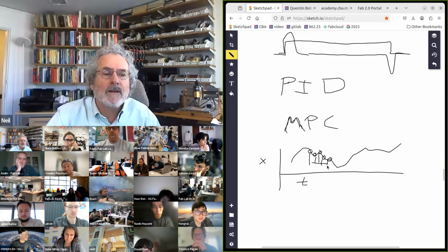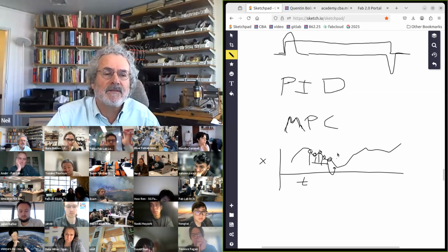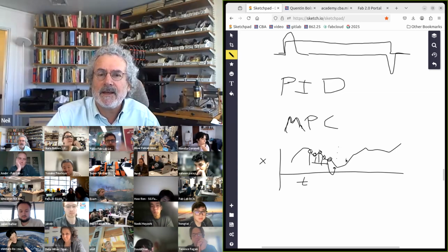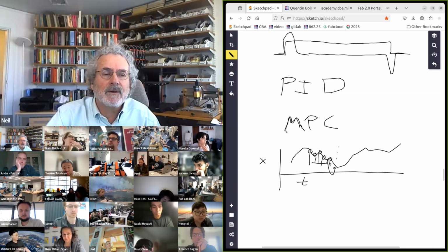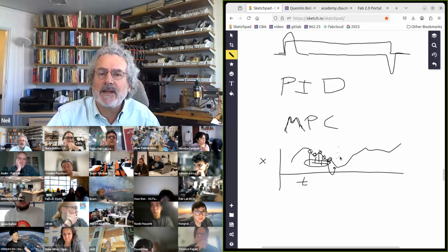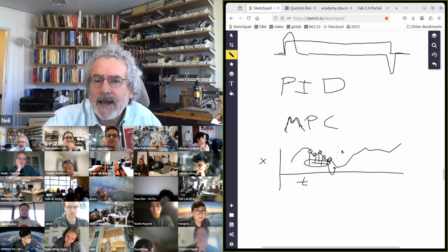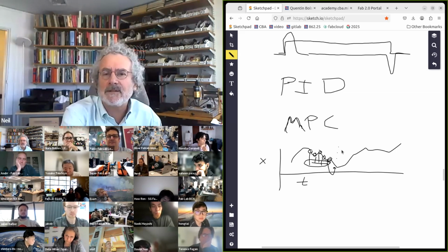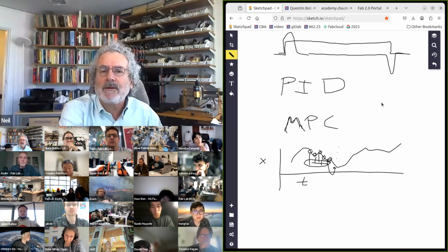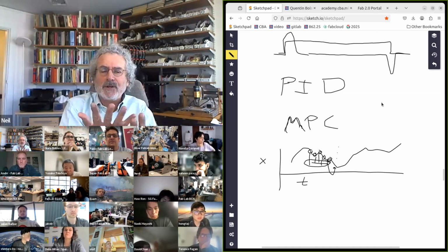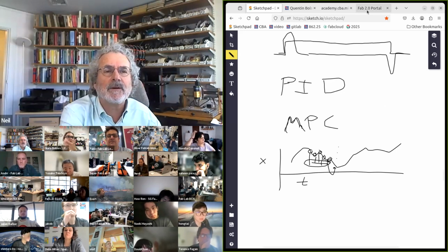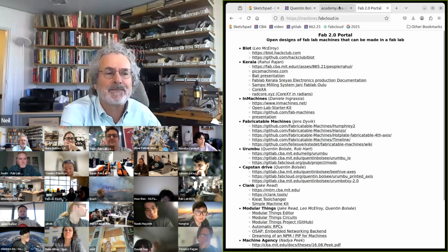And then you use all of that to predict what it's going to do next. And predicting what it's doing next is its position, velocity, and acceleration. And then you train a model that takes the past history and predicts the future of the machine. And then you use that model to feed back on how you provide the signals into it. So you can start from physical, or you can just start from an empirical one and train on it.